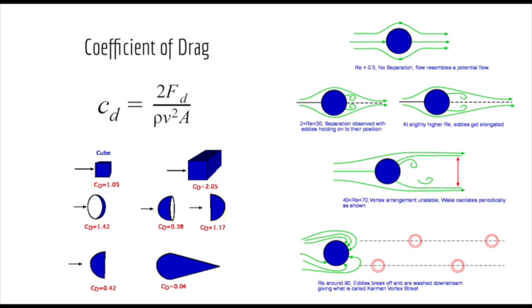We would want to treat the center of the panel as the pressure tap. If we thought of each point as the center, we would be creating stagnation points directly in front of the pressure tap, resulting in very incorrect numbers. In addition, we want the normal component of the flow velocity to be 0 at each pressure tap for our calculations. If we have our pressure taps on the corners, that could be an influence.